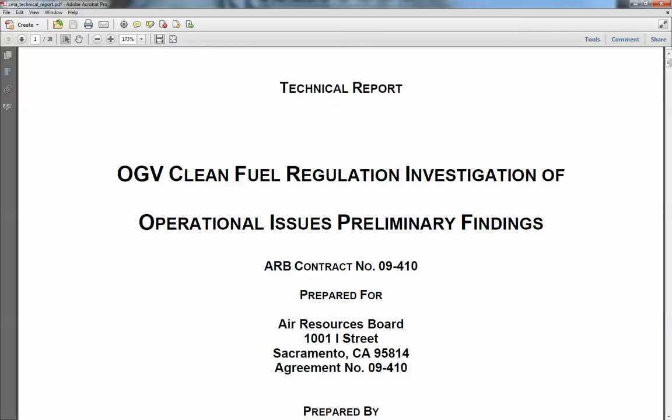Now, there are restrictions, especially in California and in Europe. In Europe, you have to burn a low sulfur heavy, and in some cases, in interior waters, you have to burn clean distillate. In California, if you're within 200 miles, you have to be burning, right now, basically a low sulfur distillate fuel. And there have been considerable problems with this. This is not a minor issue. This is a major issue right now, and it's a big topic.